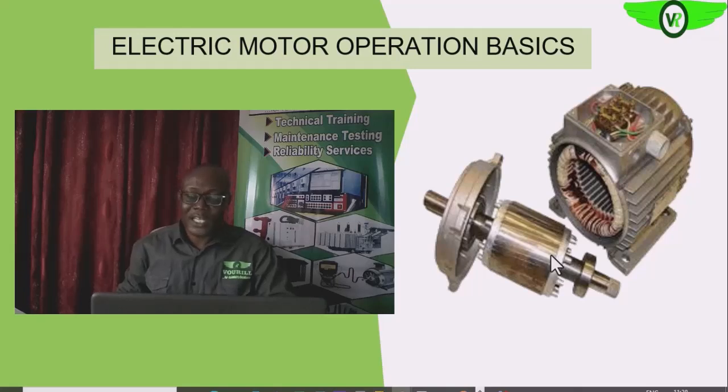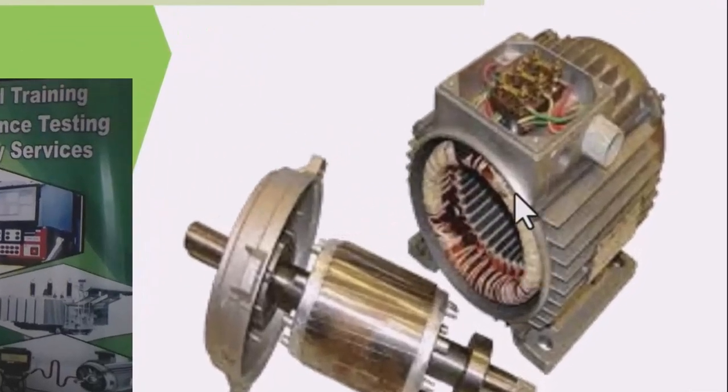Okay, it has the rotor and the stator. Each of these stators, as you can see, has windings in it. They have three-phase windings that are wound into three-phase belts. These three-phase belts are separated by 120 electrical degrees. Remember, in the course of this program, you will come to see how that affects what we are expecting.